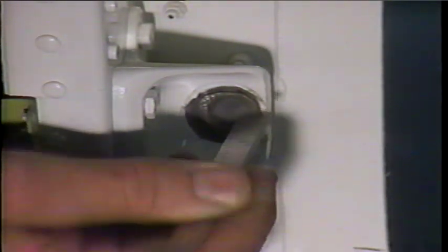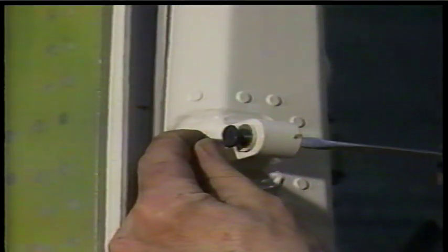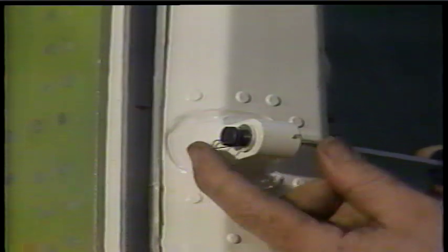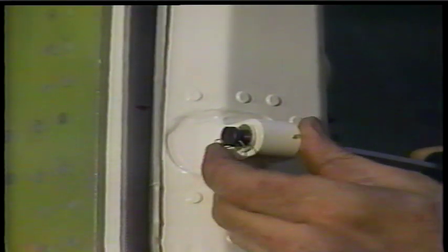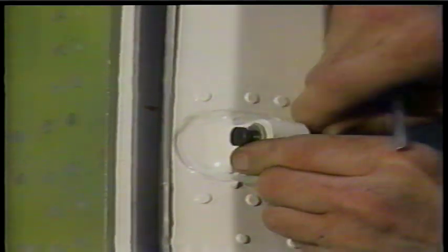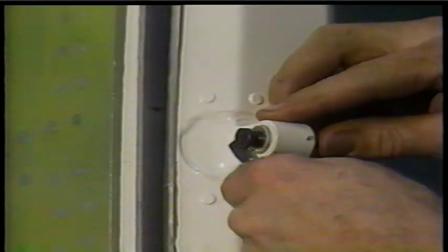The modeling clay impression records the maximum outboard movement of the door stop pins. As the latches go over center on the final latching, the door moves slightly inboard. After the proper clearance is obtained, open the door and rotate the stop pin until the nearest locking groove in the pin lines up with the locking groove in the bushing. Install the pin retainer springs in the locking grooves on each pin.